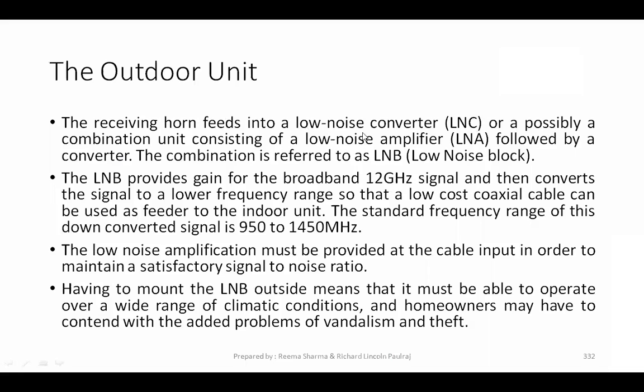It can directly pass into a low noise converter, or it can be a combination of an amplifier and then a converter. So two things here. If your low noise amplifier and converter are together, then we just term it as a low noise converter. If they are separate, then we term it as LNA and then a converter.